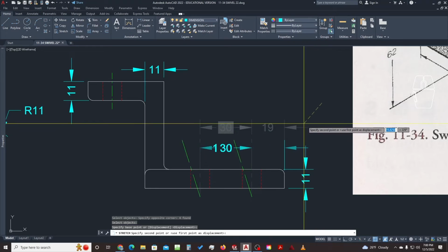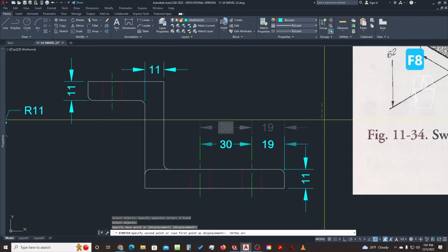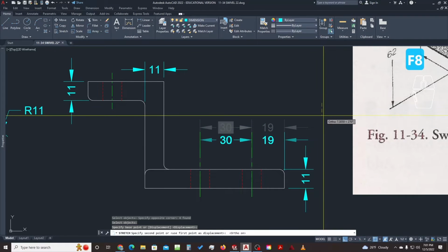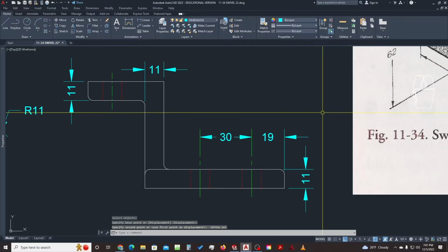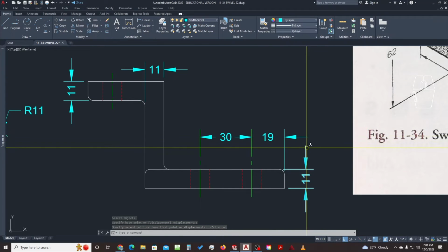and then I can just move them together. In this case, it is important to make sure that ortho is turned on. So ortho is on now, and as I move, I can move them up and down together. So I just want them a little closer to the object. I don't really want these two arrowheads to cross, so that's good enough.